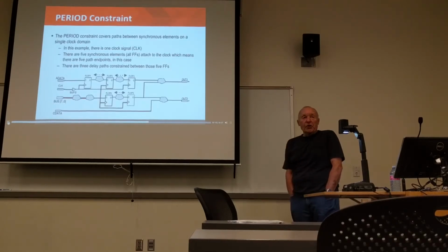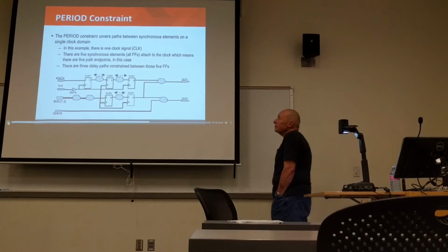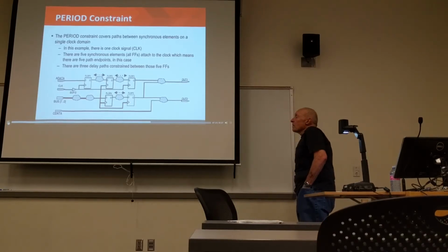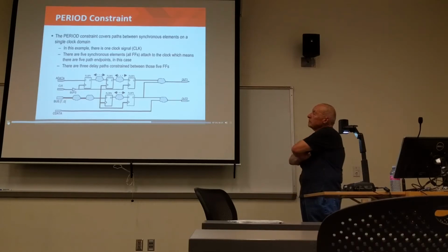This is your first constraint. There are 3 global timing constraints. The first, and most significant because it covers 80+% of internal delay paths, is the period constraint. The elements it groups are simply the synchronous elements it's attached to. In this example, there is 1 clock, and it attaches to 5 flip-flops. This defines these flip-flops as both a group of sources and a separate group of destinations.